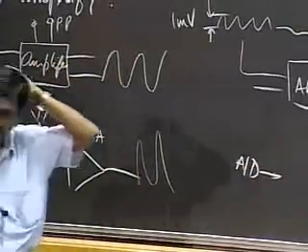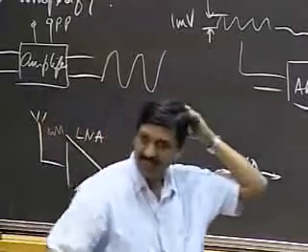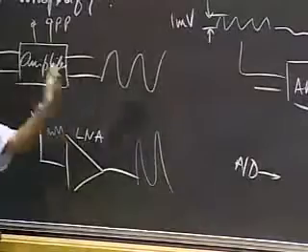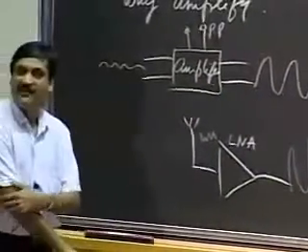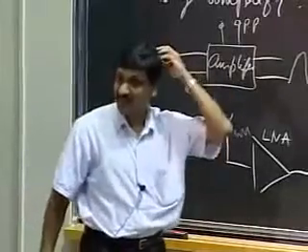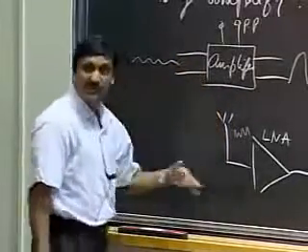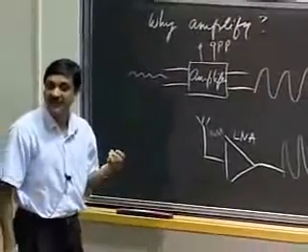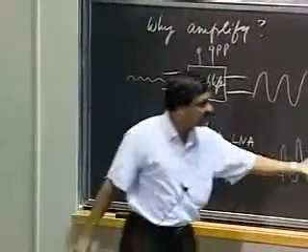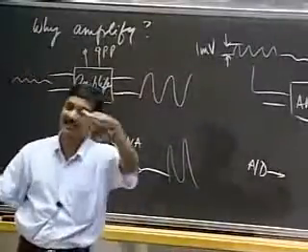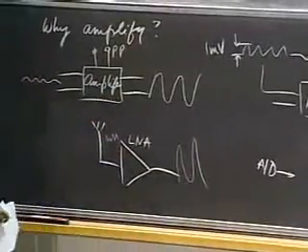I recall last week I asked somebody in class how we would transmit this signal from point A to point B without being impacted way too much by noise? And he said, oh, go digital. Good point. If I go digital, I can transmit the signal without noise being a real factor. But then the analog to digital converters need the signal strengths to be a given value before they can chop it up into digital levels.